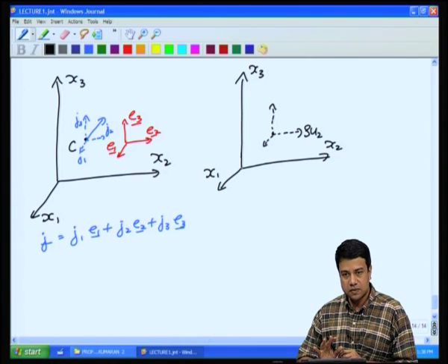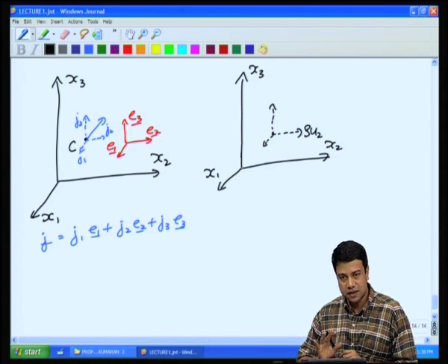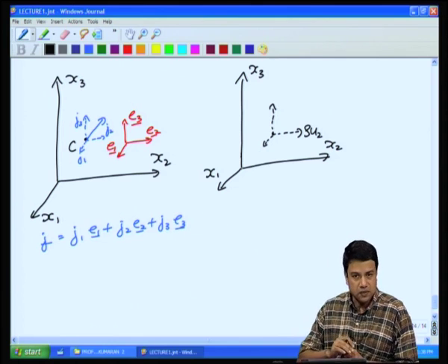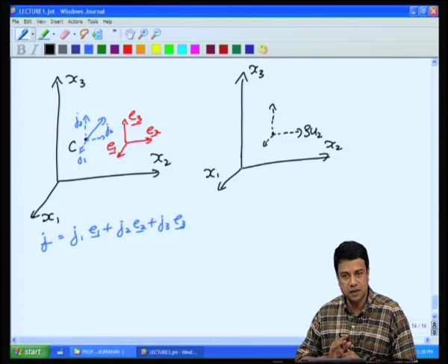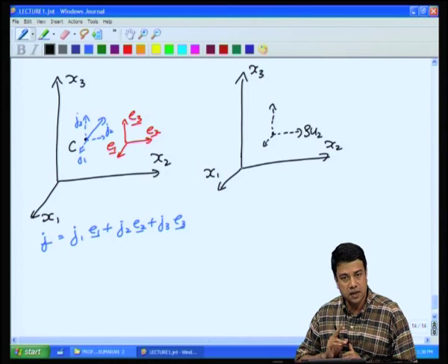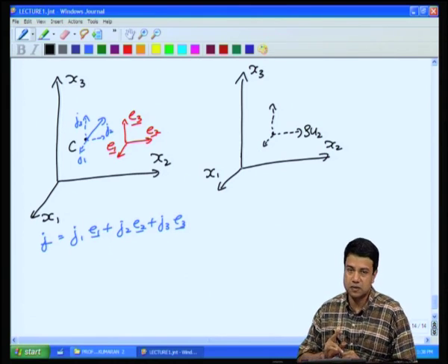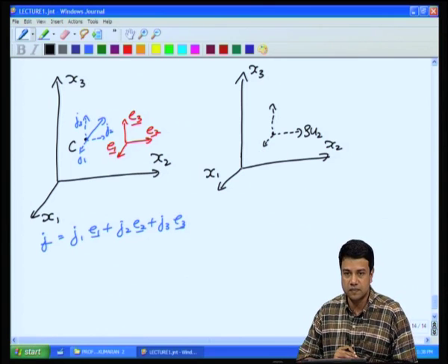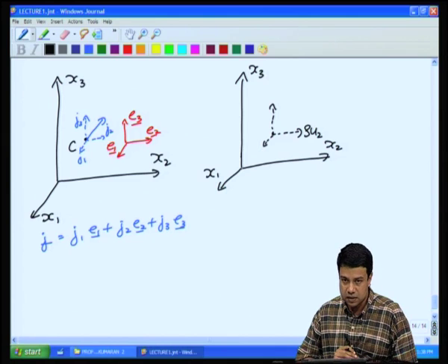This flux can also be defined as a single object. In the case of the mass flux, we had a single object, a vector, which defined the flux completely. It had one direction. That direction was the direction of transport of mass, because mass was a scalar. So, there was only one direction for the transport of mass. In the case of momentum, there are three components of the momentum, and each component can be transported in any one of three directions.